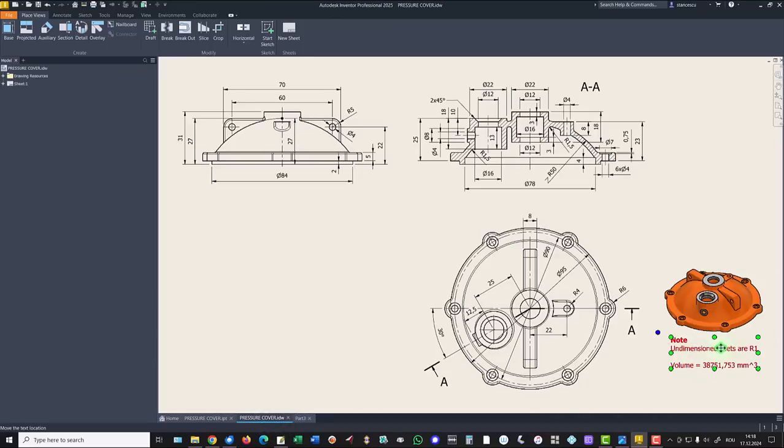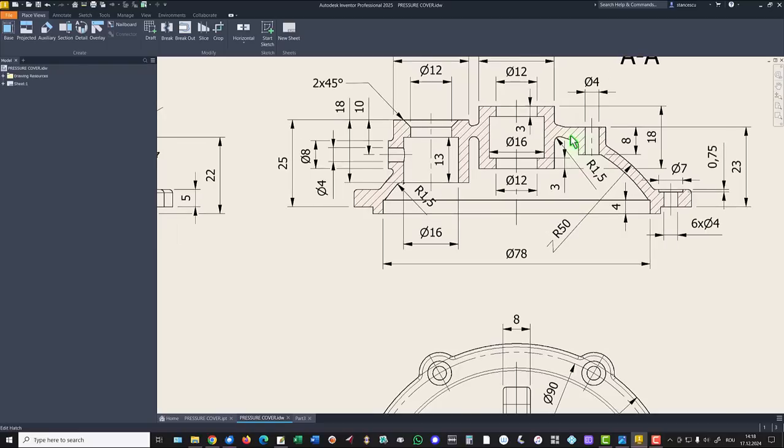Okay. Now fillets. We have this for undimensioned fillets, and there are some with other dimensions. Radius 15, this and this. 115 I said, yes. And here is also radius 115. 150, not 15. Excuse me. Good. All other are radius 1.